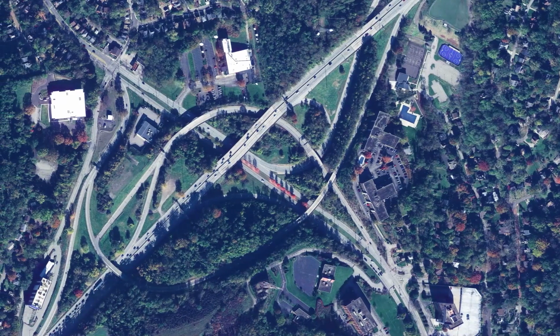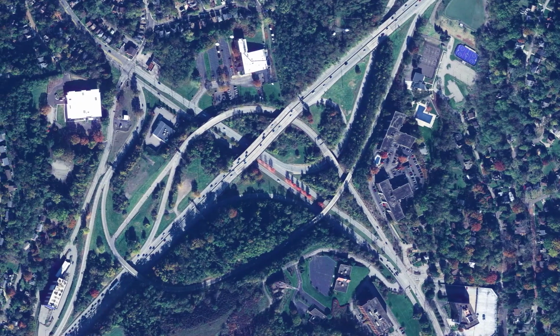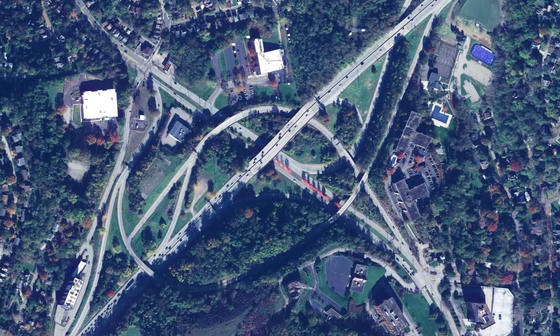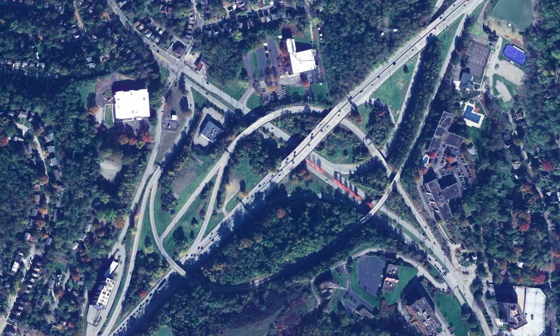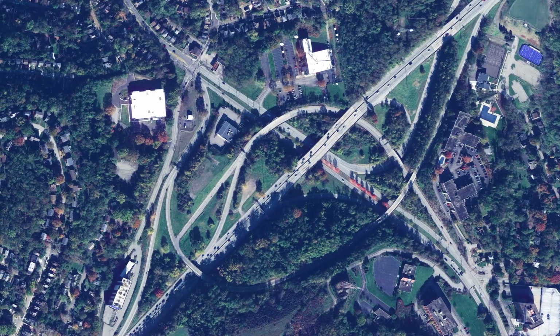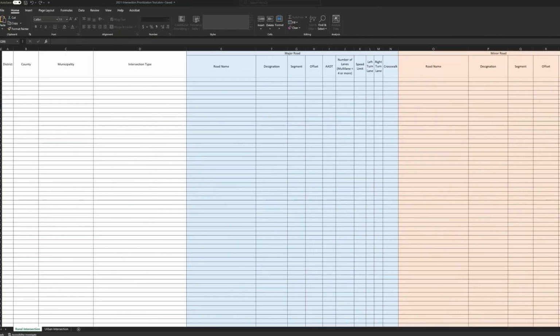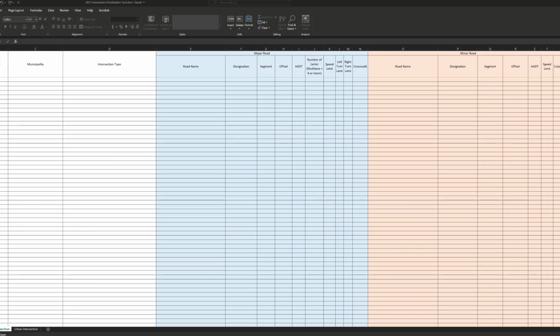We used Roadway Management System, or RMS, segments as the basis of freeway segments. We conducted a preliminary analysis of the entire state using the portion of the SPF with AADT variables. This preliminary analysis identified top sites, which we then analyzed with the full HSM method.